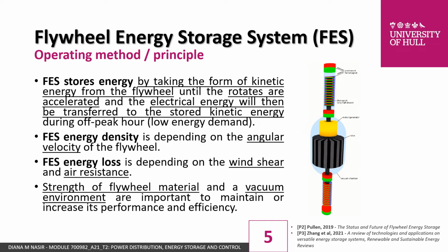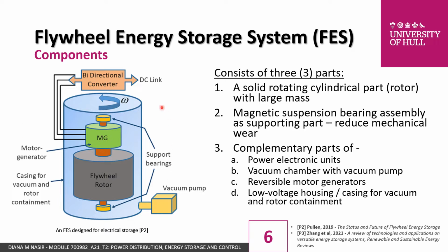So the stored energy density of a flywheel depends on the angular velocity of the system, while energy can be lost depending on air resistance or also wind shear. It's very important that the material of the flywheel should be very, very strong because of the high pressure created from the rotation of the flywheel. And a vacuum environment should be maintained to ensure that the performance and the efficiency of the system is retained or increased.